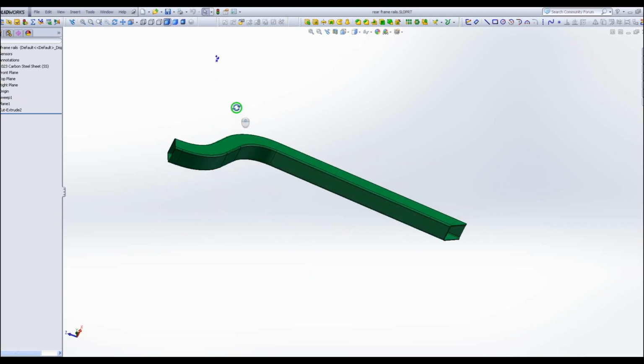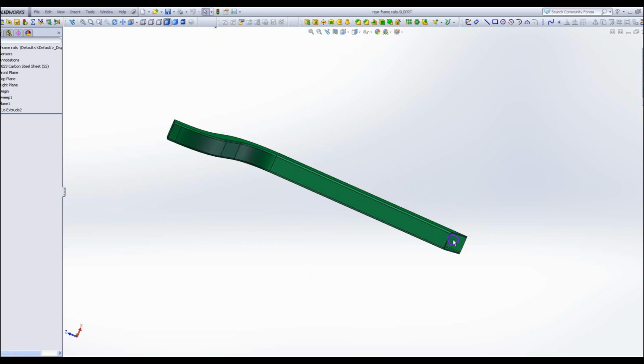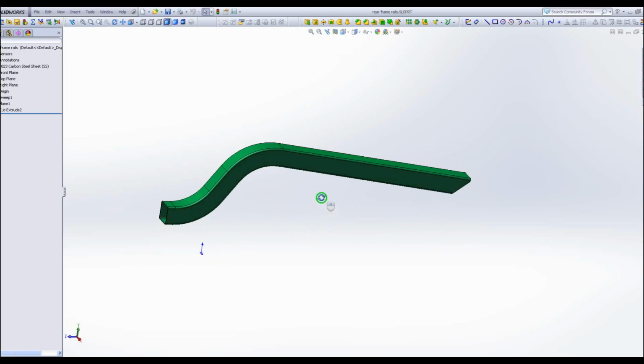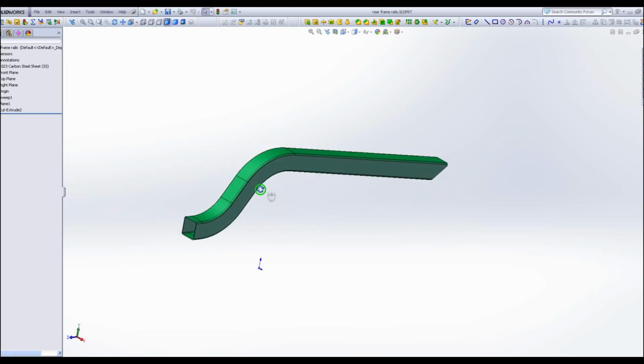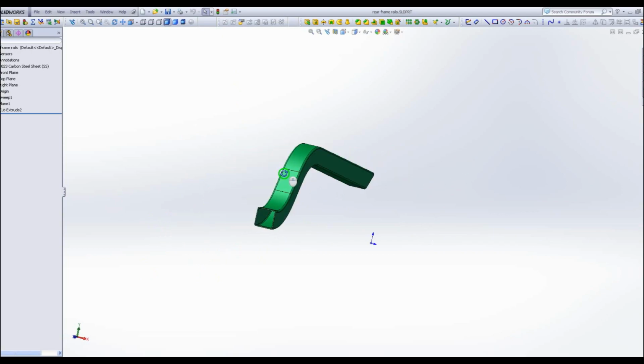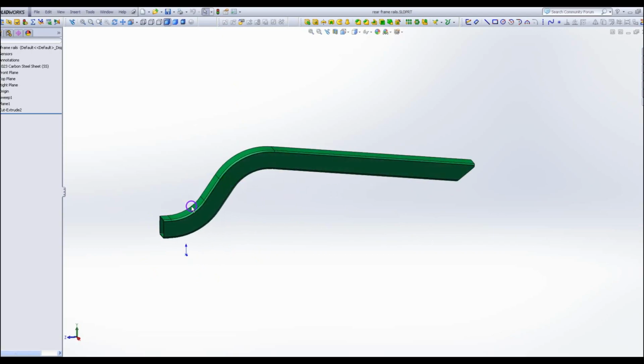And then this is basically just a piece of bar stock, 3 by 1/8 inch. And just put it on there, weld it, bend it, weld it until you get all the way back here. So essentially you're making a box section for a frame rail. And that's going to be way better than trying to bend the original.